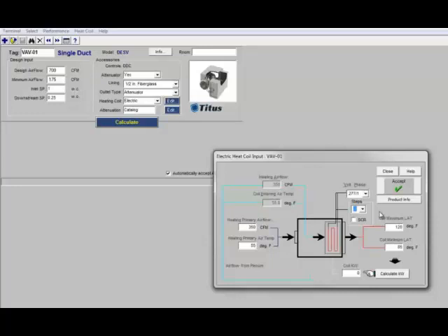Sometimes we're asked if we can build a 10-stage heater, and that's really totally impractical because that would require 10 separate elements and all the controls to operate each of those elements. When situations like that come up, that's when it's best to suggest an SCR controlled heater. An SCR heater is going to give us the same functionality that we would get from an infinite number of stages of heat, so that's going to give us the ultimate in control.